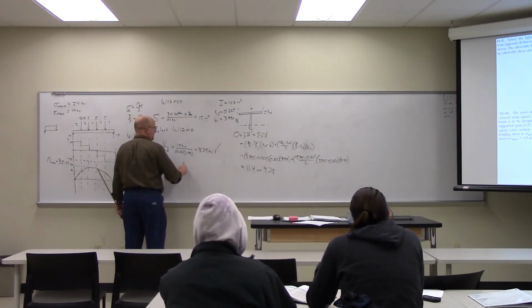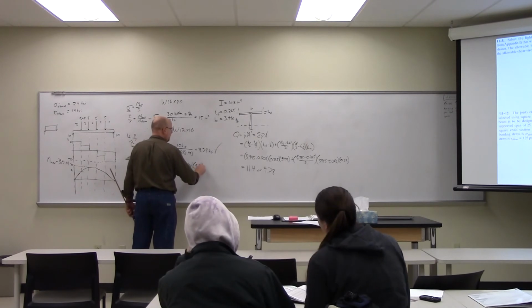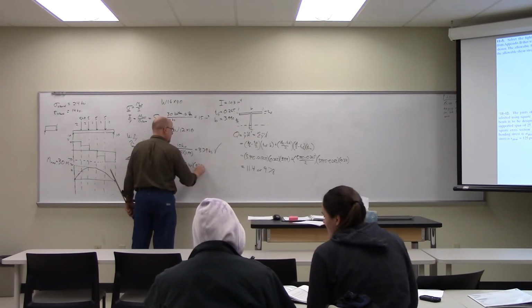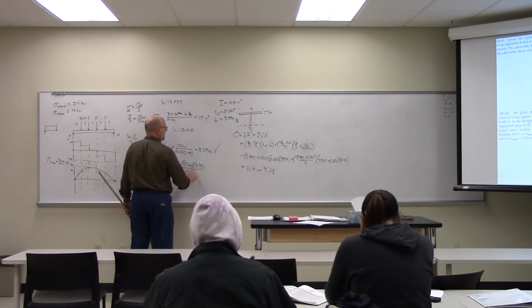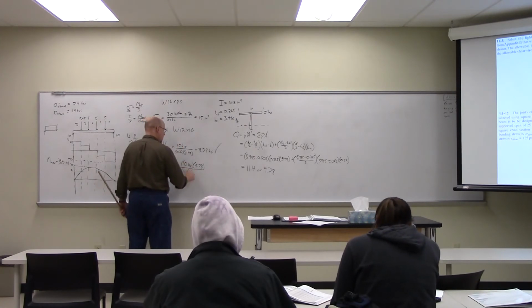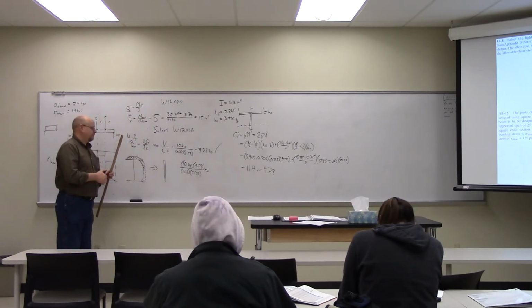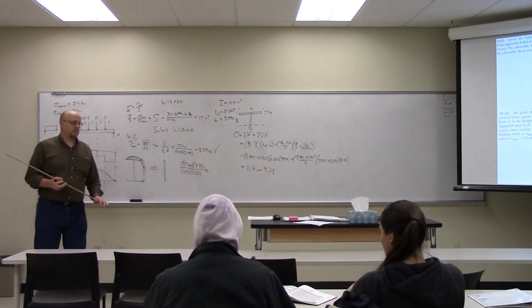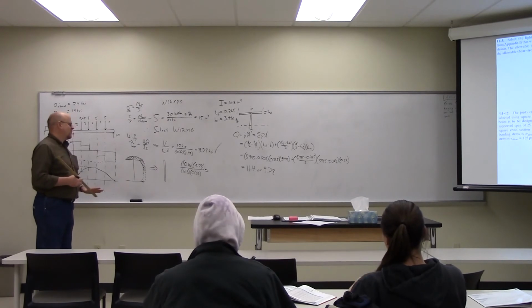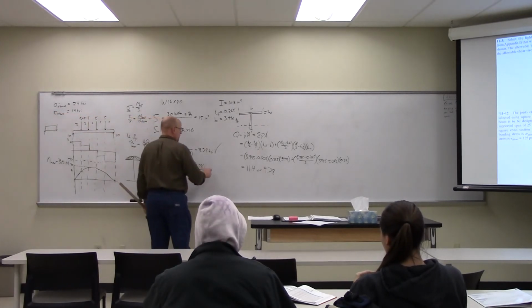Okay. So we have 10 kips times 9.78 divided by I, which is 103, times T, which is TW, taken to the web, which is 0.22. What does that give me? 4.32.